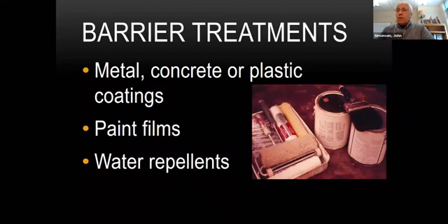Also, it's very difficult to apply water repellents that don't have some kind of pathway through them, some kind of pinhole. The same thing is true of paint. That's why you use more than one coat of paint. So water repellents do work. Once again, they don't work great, but they do improve the service life of the wood.